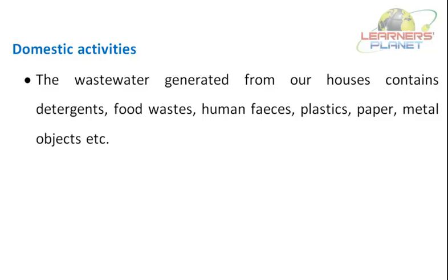Even the storm flows from rains, storms and street washings contain grit, sand, leaves and other debris in the drained surfaces. So in some communities, these flows are collected separately for disposal and they do not become a part of the community wastewater. But storm flow volume varies with the intensity of rainfall, its topography, its pavements and roof areas, and combined wastewaters are the mixture of domestic or sanitary wastewater, and these are collected in the same sewers.